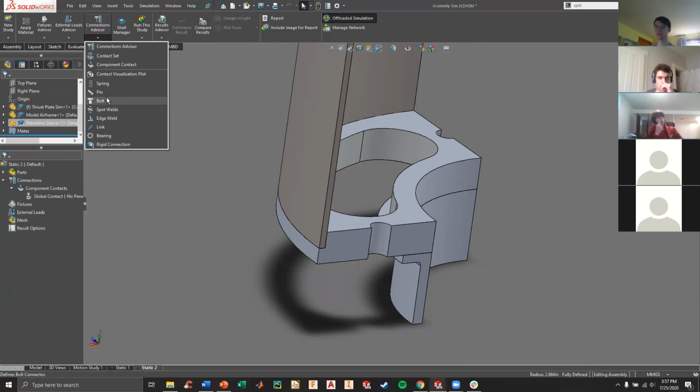And yeah, so connections again aren't overly complicated. We'll get into a little bit more of these, which are actual mechanical methods of connection, which it can also solve for. So rather than having to model a whole bolt and model all the contacts between the faces and the forces on the bolt, it will do a simplification, which will get you very good results without having to deal with all of that, depending on your use case.